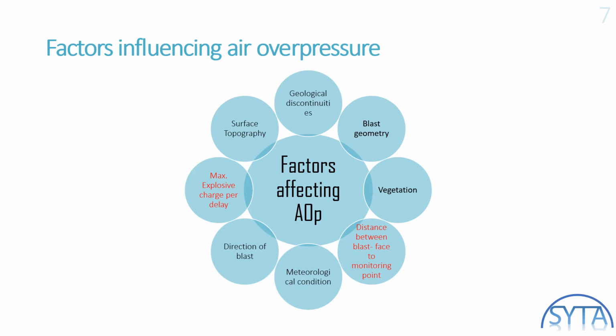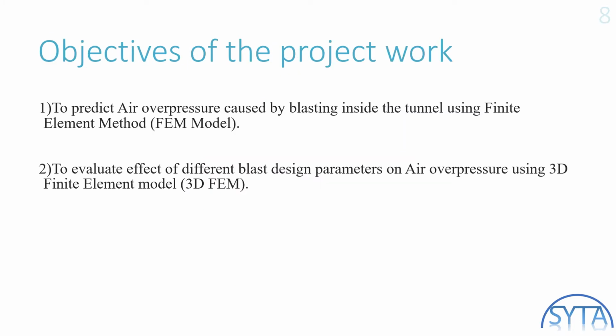Among all these factors which affect air overpressure, there are two very important factors, shown in red color. The first one is the distance between the blast face or blast source and the monitoring point, and the second one is the maximum explosive charge per delay.